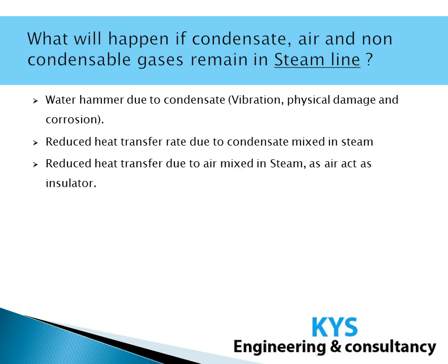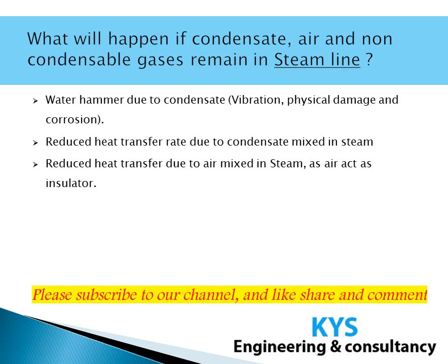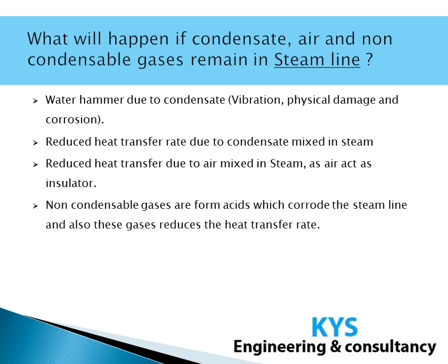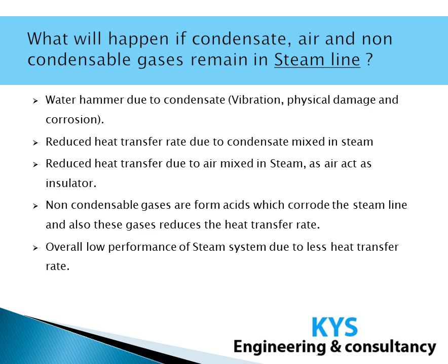Also, there will be reduced heat transfer due to air mixed in steam, as air is acting as an insulator. Non-condensable gases will corrode the system and will also reduce the heat transfer rate. Overall, we will have low performance of the steam system due to reduced heat transfer rate.